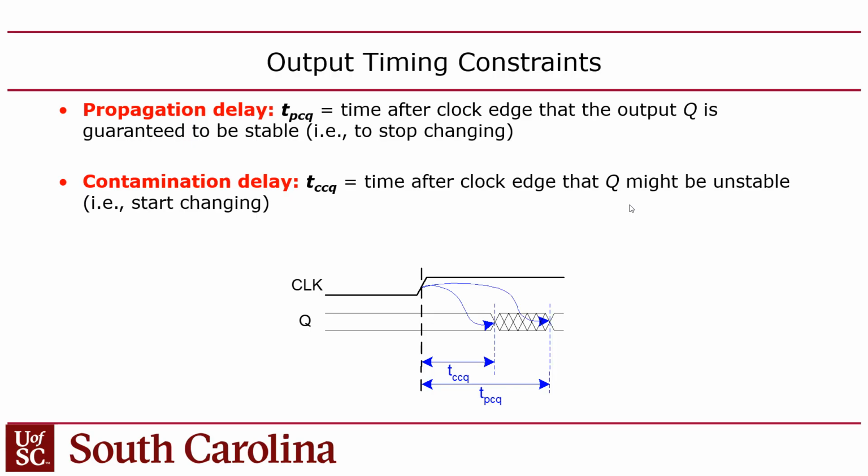Now, it's important to understand that you can't change these, because the flip-flop is a building block. The flip-flop is given to you by the technology library of whatever platform technology you're using. So in the case of an FPGA, the flip-flops are literally baked into the FPGA, right? So the performance of the flip-flop is determined by whoever designed the flip-flops on the FPGA. There's nothing you can do about this. This is just fundamental to the FPGA.